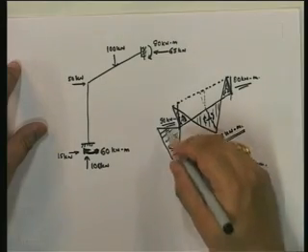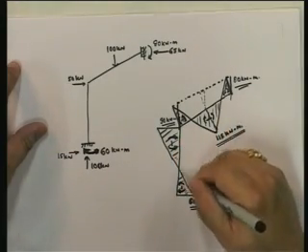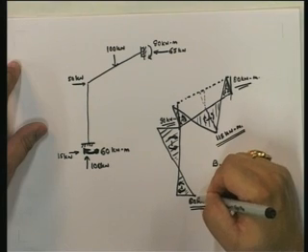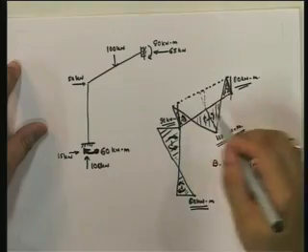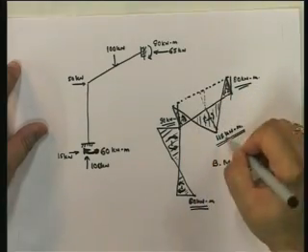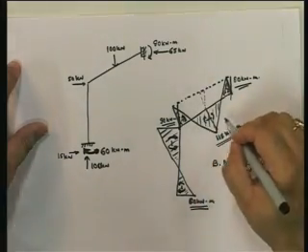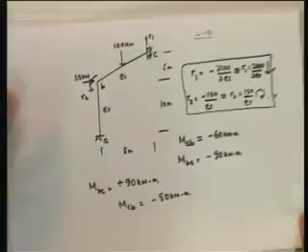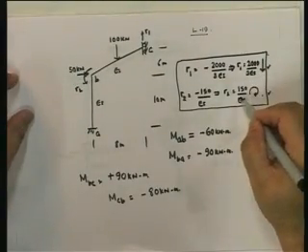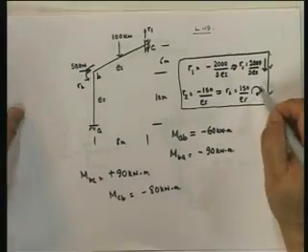I just gave you the solution to this particular problem. Now remember this solution. Interesting to note here is that almost everywhere the maximum bending moment is fairly uniform. On the right hand side it is 60, on the left hand side it is 90, here on the top it's 90, on the bottom it's 115. And the displacements are 667 upon EI, downwards, and 150 clockwise.